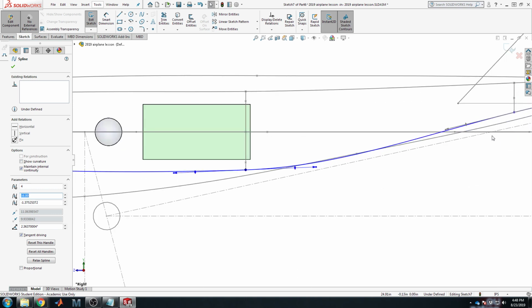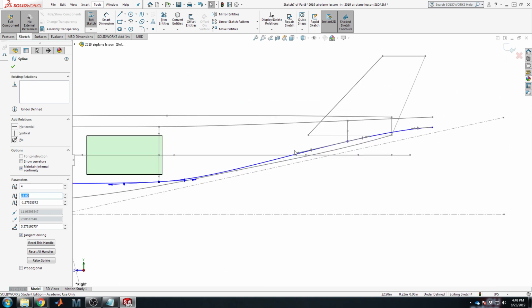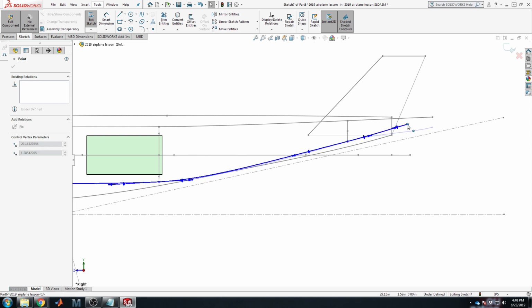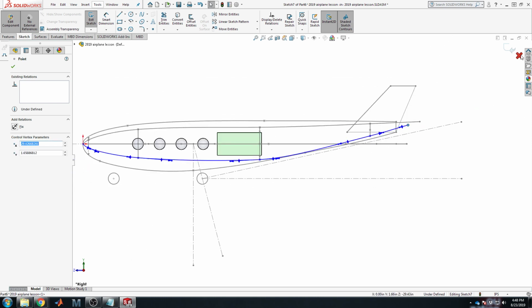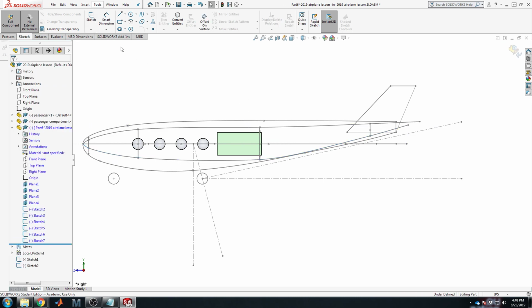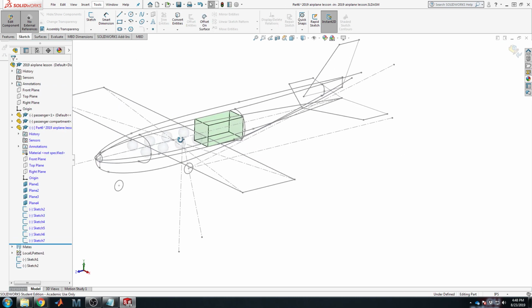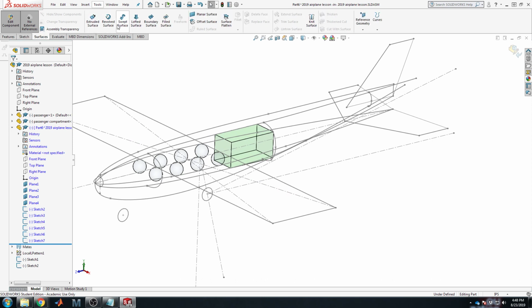Keep it relatively flat. Need to decrease this so we don't have too much of a belly back here where it should rotate. Change that angle somewhat, and actually I think this point location here is bad. I will just take it up like so. Good enough. All right. So now this time, save, as I'm doing the loft, you can go to Surface, Lofted